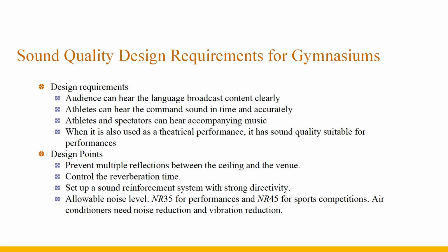The third, set up the sound reinforcement system with strong directivity. Due to the higher noise and longer reverberation time, the sound level of sound reinforcement is higher than that of general auditoriums, and the requirements for directivity are also higher. The fourth, the audible noise level is NR35 during performance and NR45 during sports competitions. Air conditioners need noise reduction and vibration reduction.